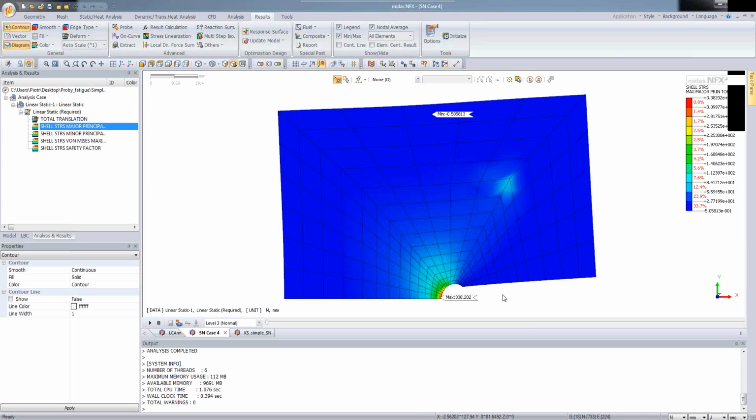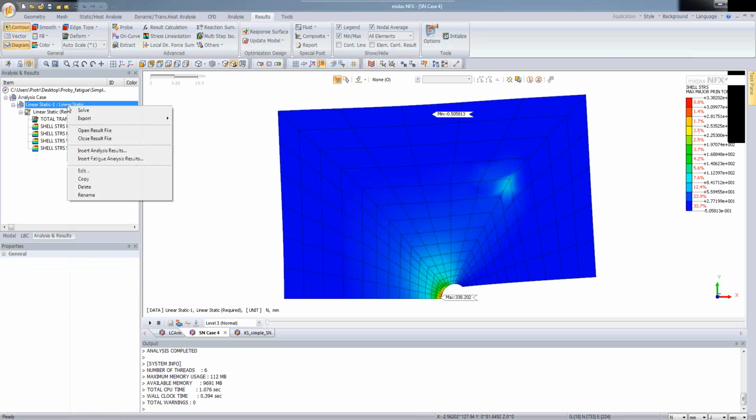And just to remind you, probably you remember from the last lecture, but I want to remind you one more time that this method, which is called stress life, is concerned with the total life and doesn't distinguish between the initiation and propagation of the crack. So crack initiation and propagation are not taken into account for this method, and this method is valid for high cycle fatigue.